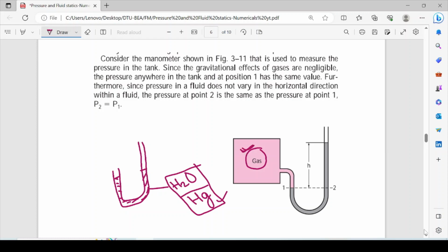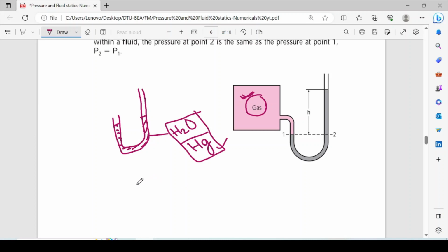For this we can write the hydrostatic law. Let's suppose that PS is the gas pressure, so we can write the equation, and we are assuming pressure is the same at all points, and this is a very low pressure. That means PS is equal to P1 is equal to pressure P2. But let's suppose that this is open to the atmosphere, and this pressure is the atmospheric pressure.